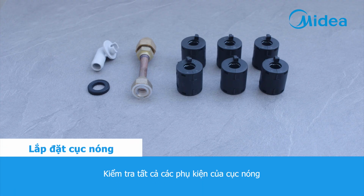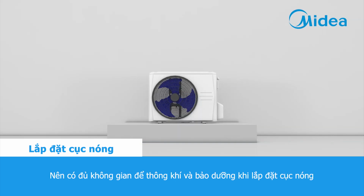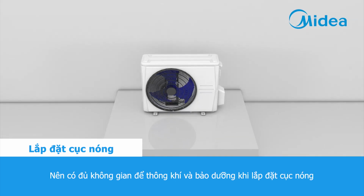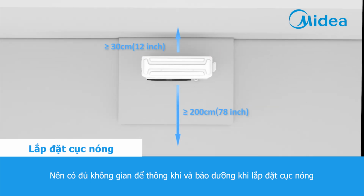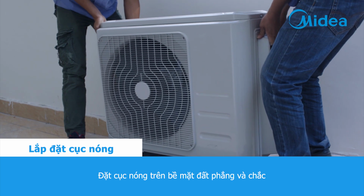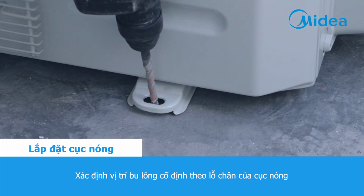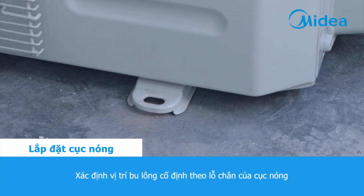Check all the accessories of outdoor unit. There should be enough space for ventilation and service when the outdoor unit is installed. Put the outdoor unit on a flat and tough ground. Determine the positions of fixing bolts according to the holes in the feet of outdoor unit.